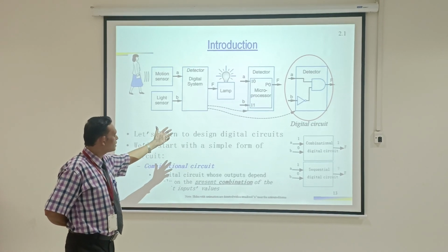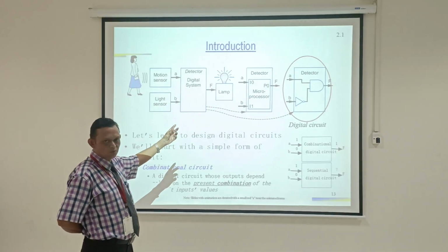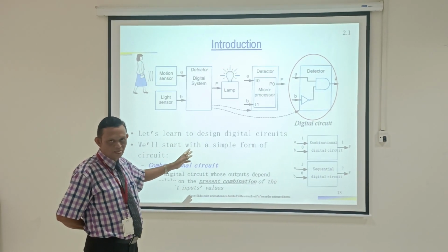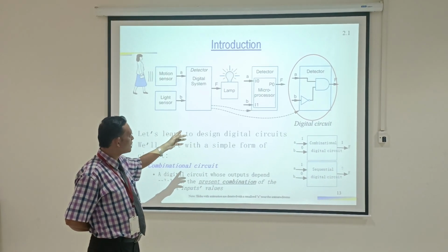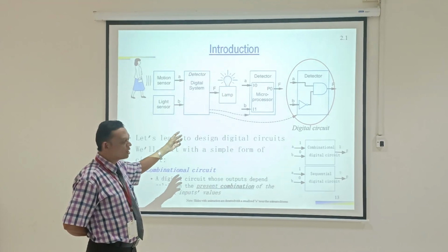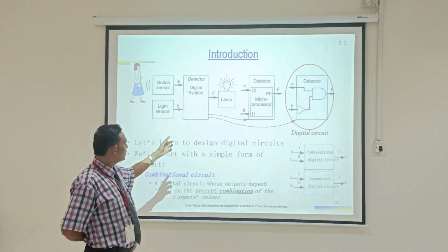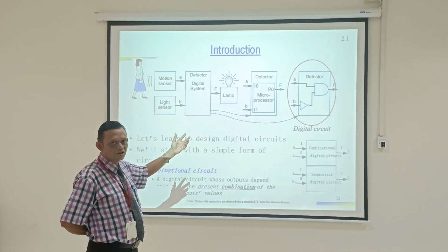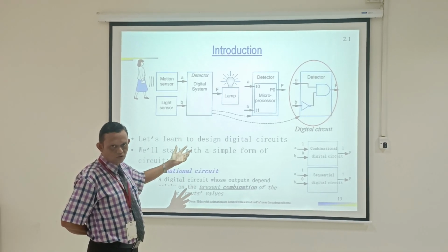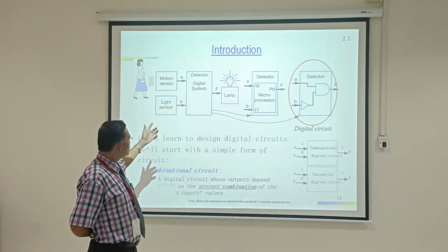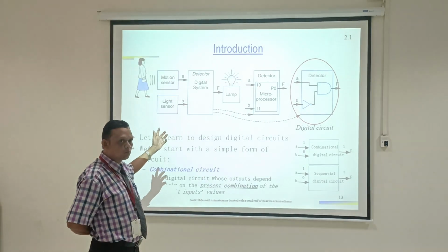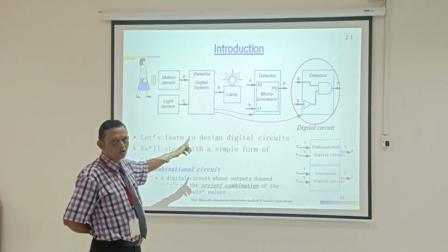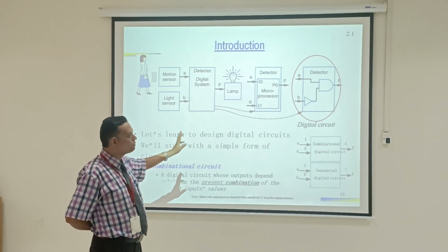When the output is 1, it has to be observed in some way. Here, for understanding the output, we are using a bulb as the output device. When F is 1, the bulb will glow. If F is 0, the bulb will not glow. Whenever either A is 1 or B is 1 or both are 1, F has to provide 1, and accordingly the bulb will be illuminated.